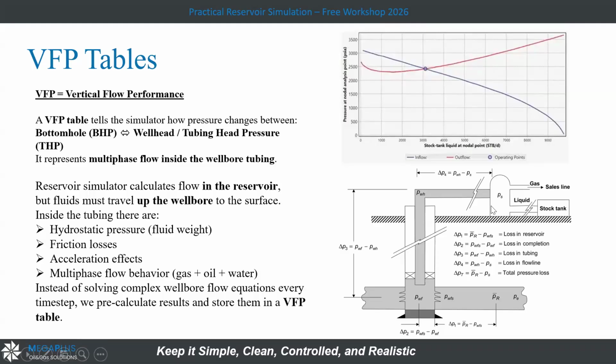But what I'm concerned with in reservoir simulation is the vertical lift performance, VLP, or the vertical flow performance. I have to put in a schedule so that at each pressure in the reservoir, the wellhead pressure will be figured out. As an example, if I have 3,000 here, at the surface it will be 3,500 in case of gas. In case of oil, it could be 1,500. It's a schedule that I inserted. So when I make the history match, I will match the wellhead pressure as well.